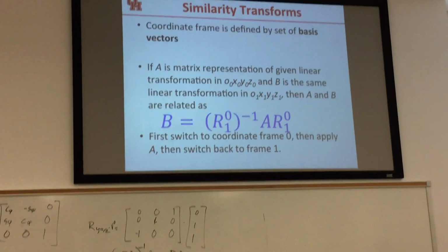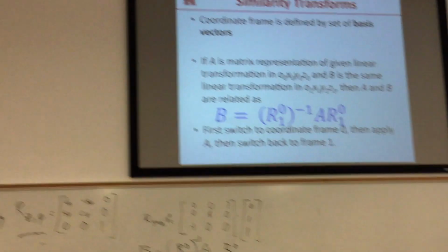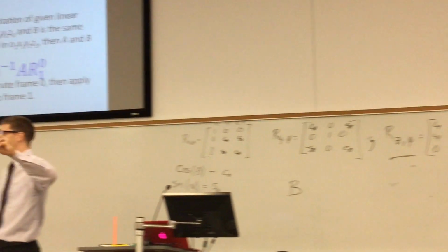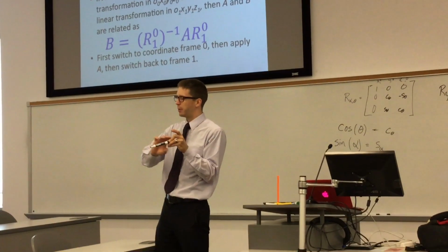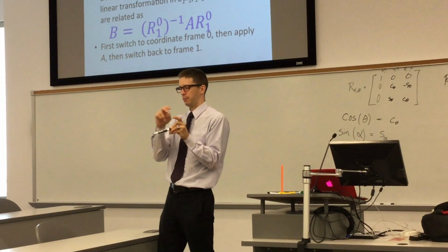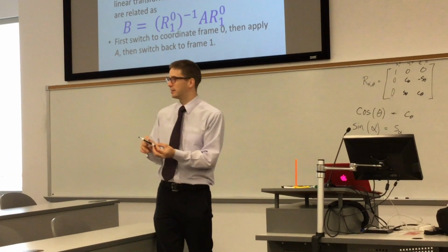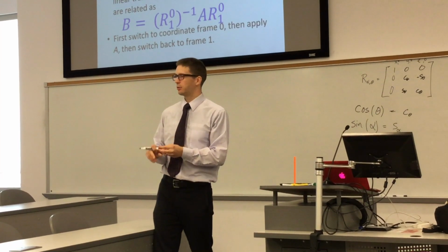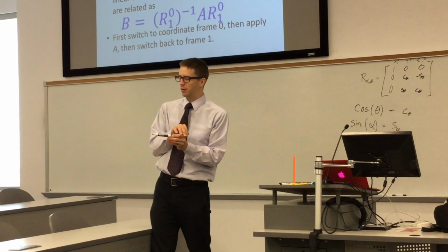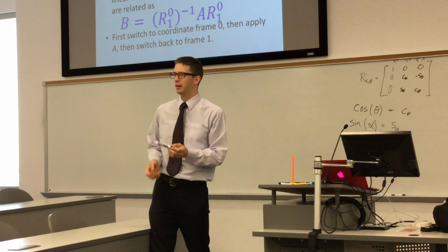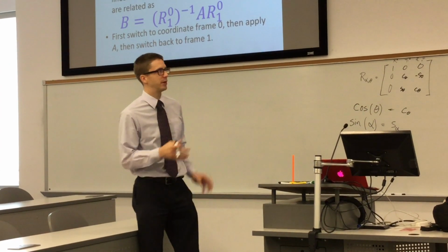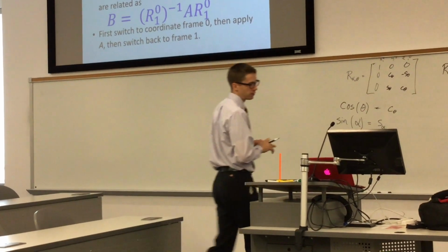When we've got a robot arm, and I bolt a tool onto the end of the robot arm, there's some sort of transformation from the gripper to the end of the tool. I have to be applying the similarity transform. So if I know the transformation from one to the other, I've got to find that full transformation. I've got to apply the pre and post multiply.